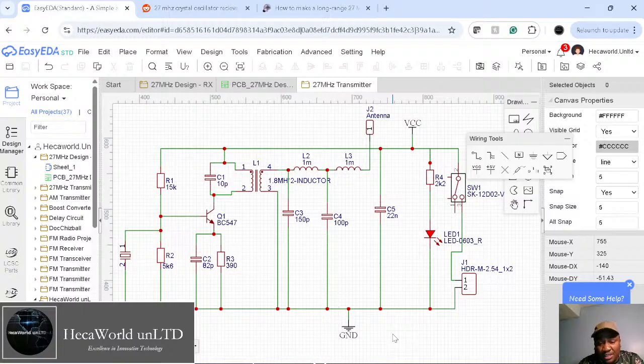And so if you're using this, some of them can even go lower in some countries from 79. But what if you use this, you can be rest assured you're gonna get interference at 108 megahertz if you don't use the filters. So you need these filters. And some TV receivers also operate at lower than 100 megahertz, so maybe like 50 something megahertz, 57, 54 megahertz. You could have interference on TV receivers unintentionally.